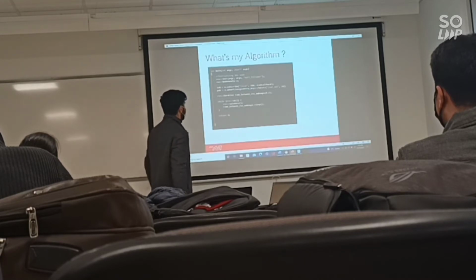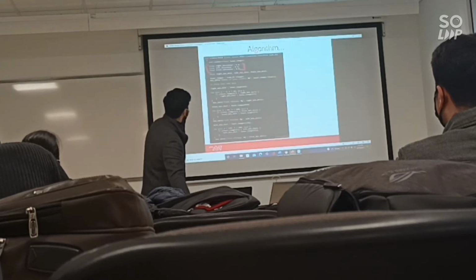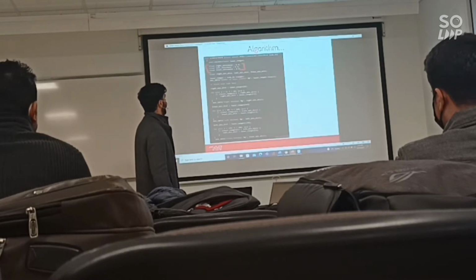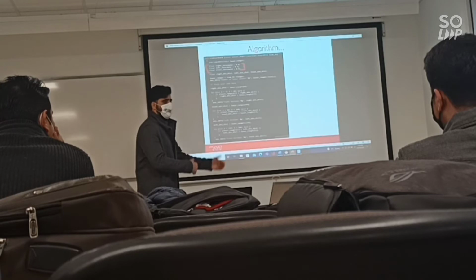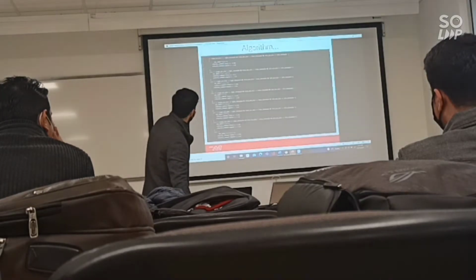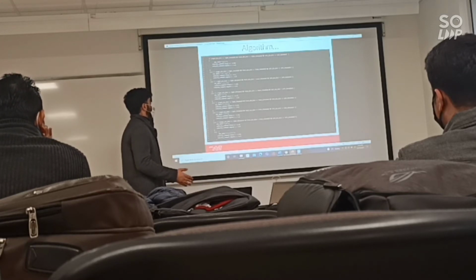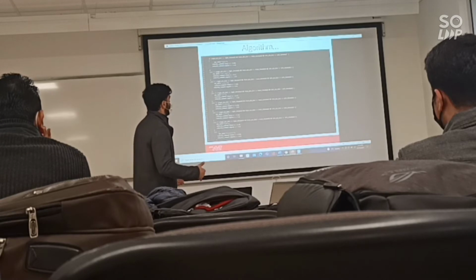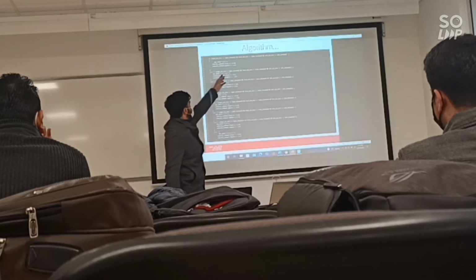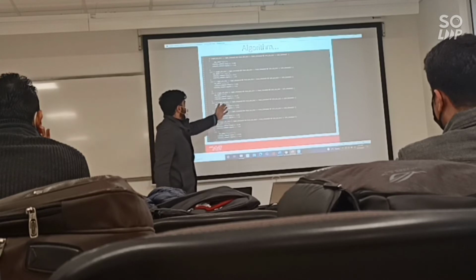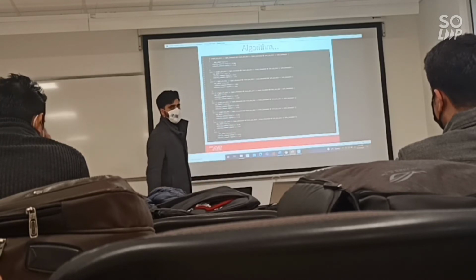First I have used the scanning. The laser is scattering the rays using this function. I'm calling this function, and I'm setting the minimum threshold for the right as 0.4 meters, for the left as 0.4, and for the front 0.8 meters. I have used this logic of 8 different gate combinations. If my right minimum distance is less than threshold, my front minimum distance is less than threshold, and left minimum is less than threshold, then stop and just revolve. I have these 8 combinations, and I have used different velocities by checking the robot's behavior in Gazebo.